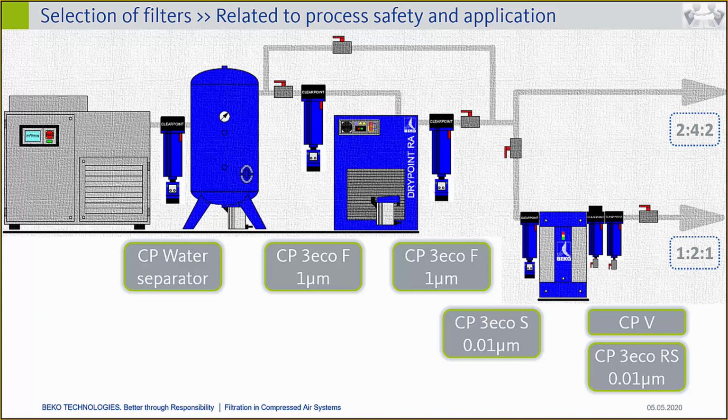But honestly, I have no idea what the pressure drop in the sterile filter element would be in a regular maintenance period of half a year or 1 year. I can assume that this is totally different to our regular coalescing filter elements. But if that was the only way to achieve class 1 in terms of particles, then that might be a solution, although it's very cost intensive, because the sterile filtration package includes the stainless steel filter housing and the stainless steel filter elements.